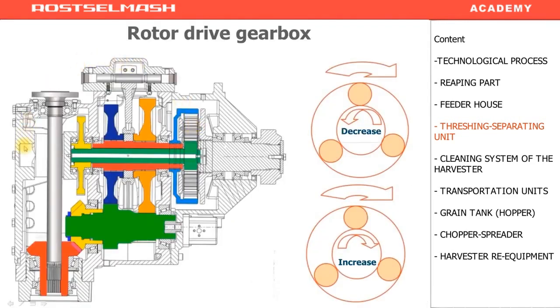The rotor drive reduction gear looks like this in the section. This is where the driveline goes. On this side, the hydrostatic transmission pump is installed. When the driveline rotates, it rotates the shaft, thus it rotates the pump. Only when the rotor is activated.